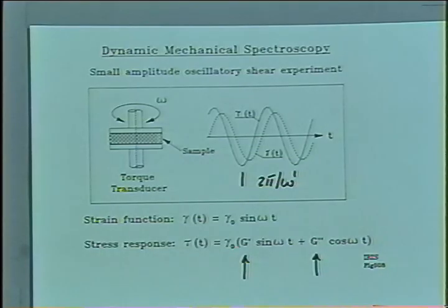If you would just look at stress relaxation, you will get G of t. You have a single function, and you will have a hard time determining the spectrum from that single function. The same thing with J of t. And that's a simple fact, and we learned that the hard way.